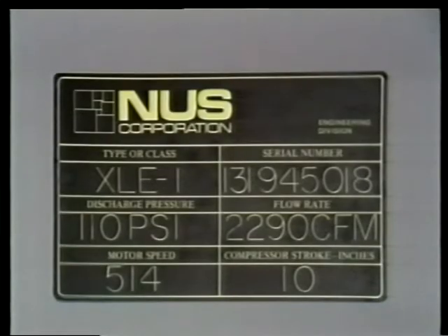Discharge pressure is how tightly the air is packed together when it leaves the compressor, and it's measured in pounds per square inch or kilopascals. That's a metric unit. On the average, positive displacement air compressors can generate higher discharge pressures than dynamic types. Most compressors are labeled to show their rated capacity. The label shows the compressor's maximum rated flow rate and its rated discharge pressure.